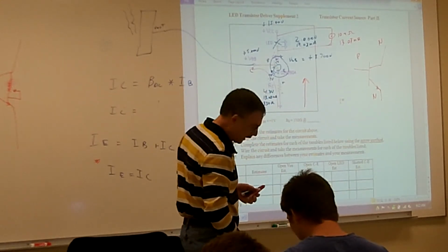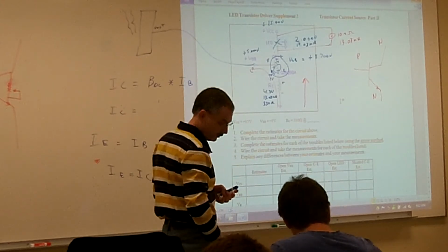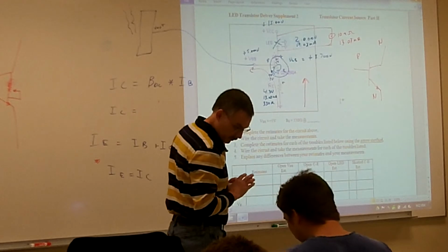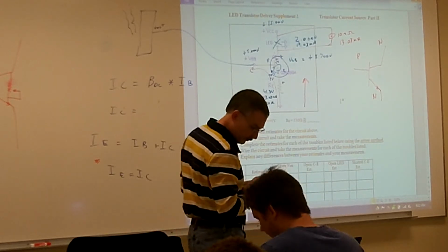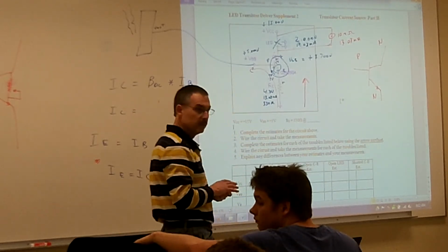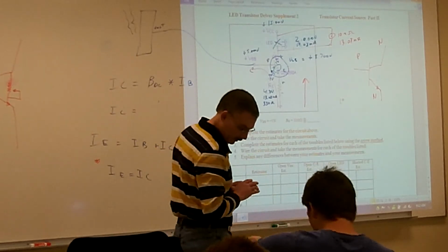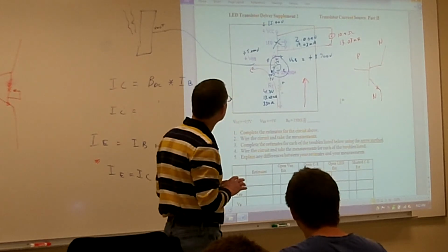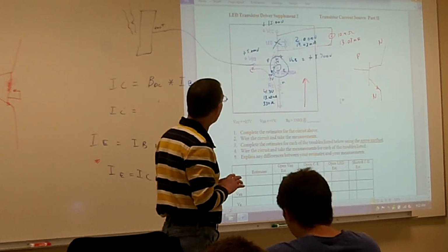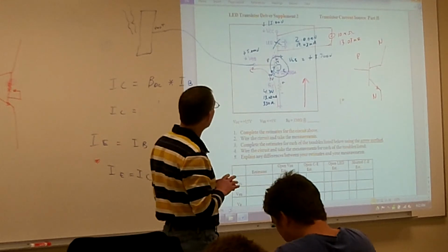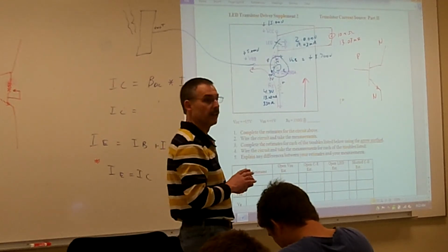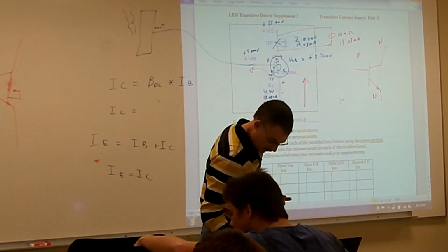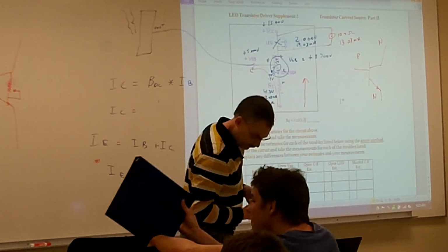All right, then my voltage of my collector, what's that going to do? Go down to 0. Is the LED on? No, it's not even in the circuit. Is Q1 on? Do I have any current going through the emitter to the collector, with that LED being open? No, so it would be turned off. Base is forward biased, but it'd still be off.